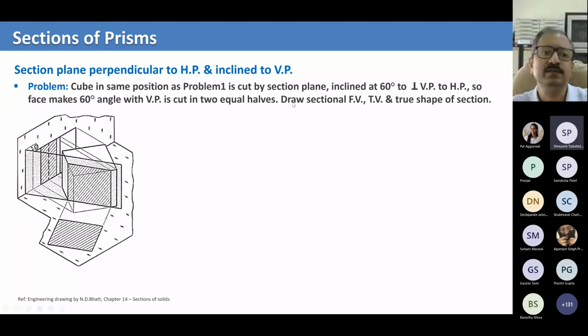Don't worry about angles and things like that. But this phi is what we're talking about, 60 degrees to the vertical plane. Okay, this is a cross-sectional plane. This is at 60 degrees to the vertical plane. That's clear. Now, when you project it, the cross-section is this one, right? When you project it onto the vertical plane, obviously the projected cross-sectional view is much smaller than the actual cross-sectional view.